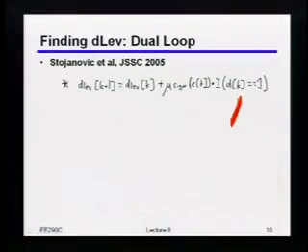The only caveat, which we'll get into in a second: notice that when I did this, I only had my updates when my data was actually a 1. So if I had a really bad bit error rate and I was getting a lot of zeros when my data was a 1, then maybe it wouldn't converge. But the good news is, I need to be making mistakes about half of the time to not go in the right direction. My dither might be horrible, but to really not go in the right direction is pretty tough. I'm sure you can come up with conditions where it would not converge, but for all practical purposes, if your link was going to work, it'll converge. But those are both great questions.